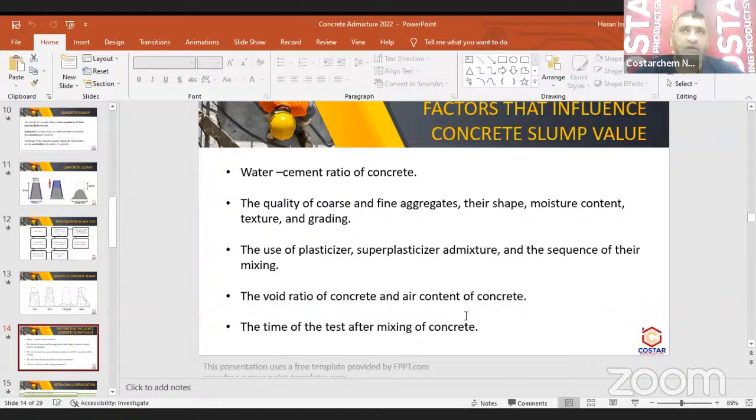Now, the entrained air is in the size of 10 to 100 microns. Sometimes it can go up to 150 microns, which is acceptable. Each 1,000 microns equals 1 mm. So when I say 10 microns to 150 microns, these are very, very small bubbles inside my concrete.